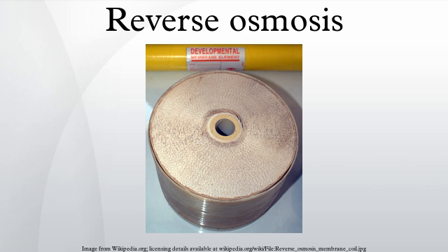There are also biofouling inhibitors, which do not kill bacteria, but simply prevent them from growing slime on the membrane surface and plant walls. Pre-filtration pH adjustment. If the pH, hardness and the alkalinity in the feed water result in a scaling tendency when they are concentrated in the reject stream, acid is dosed to maintain carbonates in their soluble carbonic acid form.